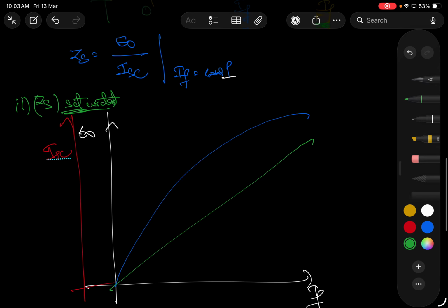So what is saturated here? The saturation condition. The word saturation is relevant to which parameter? Magnetic flux, yes or no? If the field current is increased up to 100%, then the flux will reach 100%. If the field current increases beyond its rated value, flux will not increase. That concept we call saturation. If there is no saturation, the characteristics for the EMF generation will be like this.